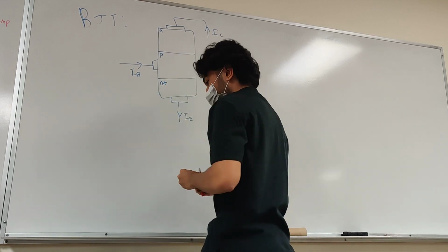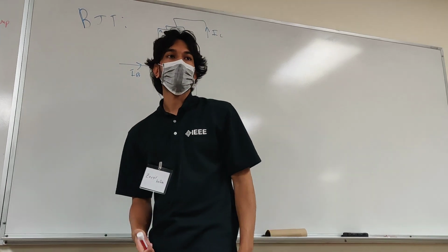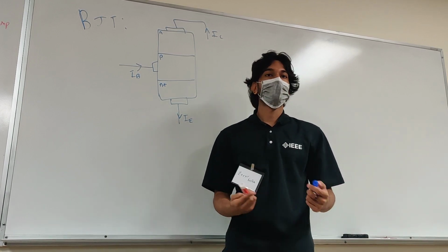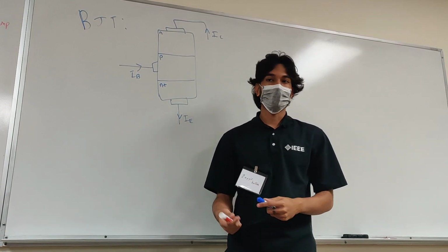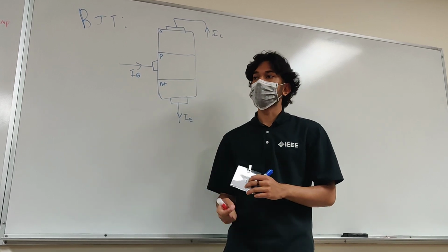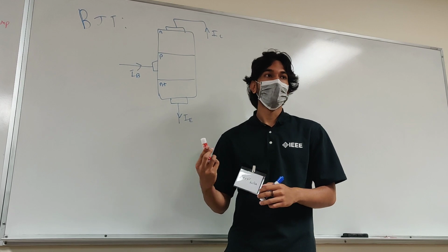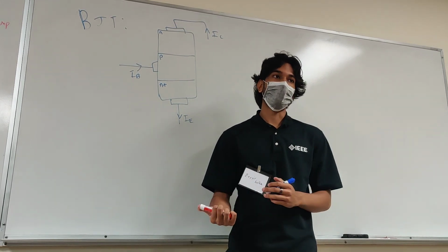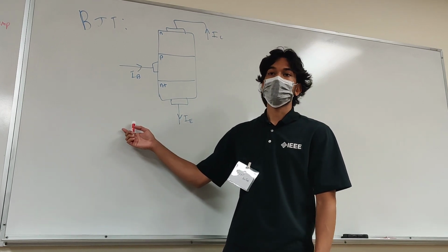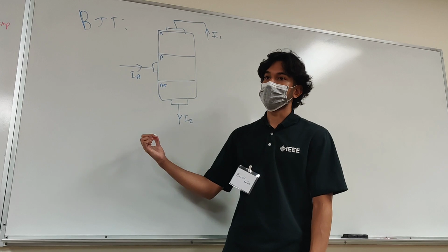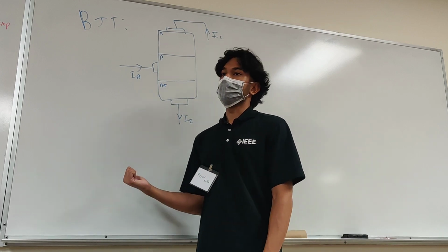Okay, so before we dive into a BJT, let's first talk about the need for a transistor. So far throughout maybe your circuit courses, you've seen resistors, capacitors, inductors, but these are what we call passive elements, which means we don't get any gain from them. We always see loss going through them, whether it's via voltage or current loss. We don't have a gain of power, and that's something we want to find. We want something that can give us power gain. So, what do we do?